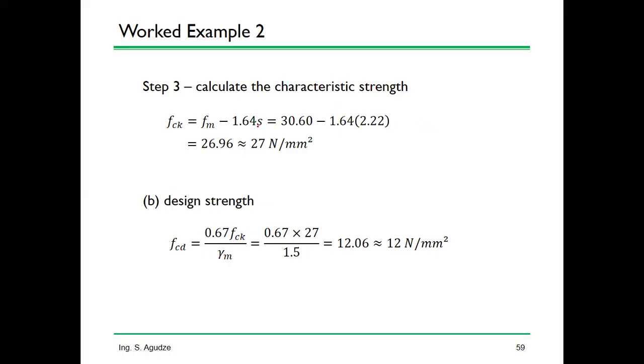If our expected strength is C25 and we have got 27, great, it has passed. So we can now use that ratio for the work. So you see how it works. It's not just on face value, but goes beyond that. And I believe if you have been given various values, you should be able to do this calculation. Okay? Any question?